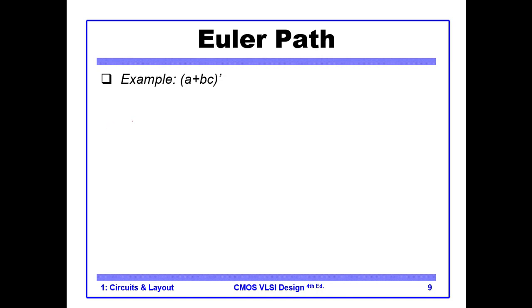We have this (a plus b c) whole bar, and we want to implement this circuit. So first go to the static CMOS circuit, or let's say just CMOS circuit. Why do I have it in static here? Because later in the course we will study dynamic CMOS circuit, but for the moment let's say we want the CMOS circuit. Okay, so we have B and C, and the B and C are ANDed, so they are in series.